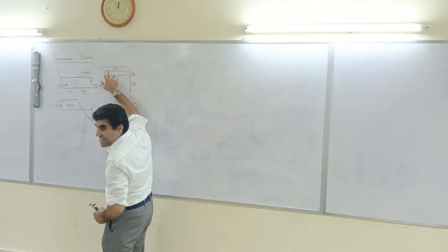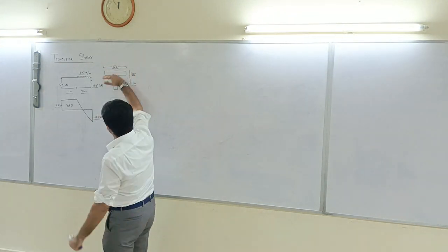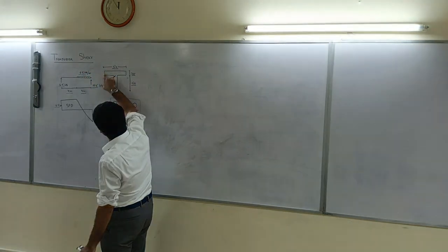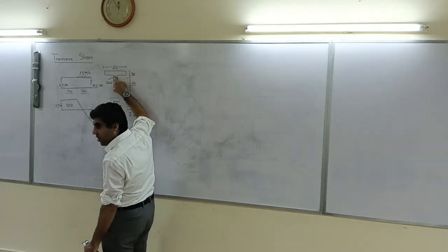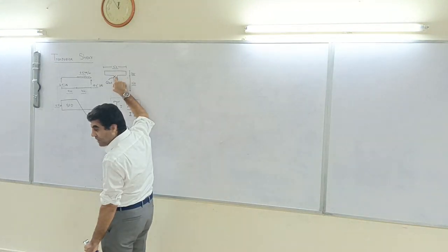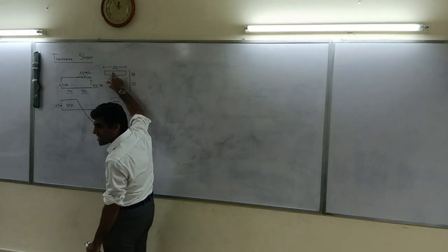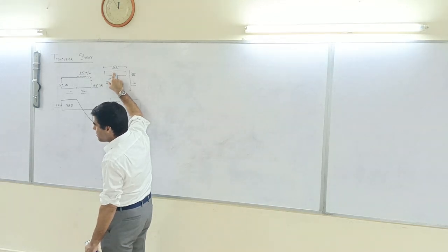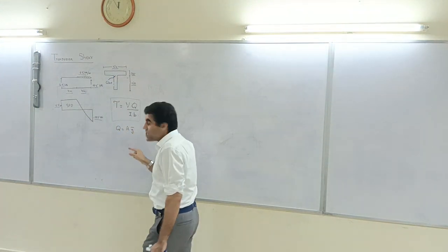So we will be taking this area, the area of the flange. Why? Because this is the area we are interested in. The point of our interest is covering that area. The shear which is resisted by that area, that is actually the shear which we can get from here. So that is actually the shear strength.